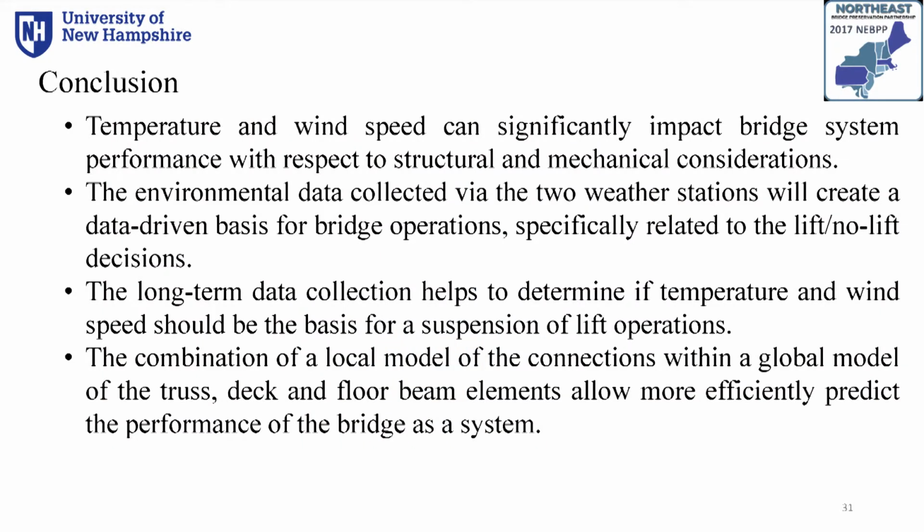As conclusions, we confirm that temperature and wind speed can significantly impact bridge system performance with respect to structural and mechanical considerations. The environmental data collected via the two weather stations will create a data-driven basis for bridge operations. The long-term data collection helps to determine if temperature and wind speed should be the basis for the suspension of the lift operations. And the combination of local models of the connection with the global models can be used to efficiently predict the performance of the bridge as a system.